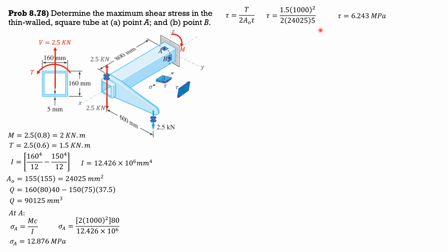The maximum shear stress at A therefore is the square root of sigma over 2 quantity squared plus tau squared. So tau max is the square root of sigma over 2 quantity squared plus shear stress squared. Remember, this is the radius of the Mohr circle.